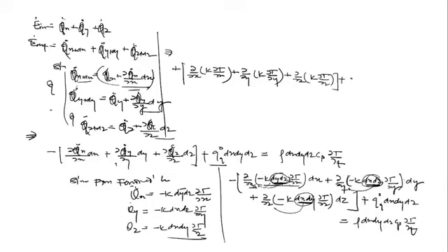I will just take outside here, in every term there is dx dy dz, so it will come out, and I will divide the whole equation by dx dy dz, then it cancels out, and everything here will cancel. Then only qg dot is there, equal to rho cp into del T upon del t. Clear?